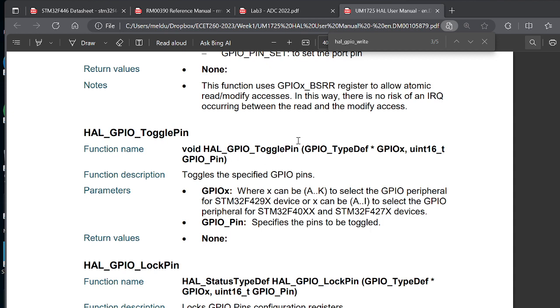And again, I've had some of you say, let's say it's on port B, pins 15, 14, 13, or what have you. And so you could call it GPIO-B, and then you could call it just pin 15, for instance. Or actually, the bit 15. And so you could do that. I said, hey, when you go and name your pins, the reason for naming your pins is it abstracts it from the port.